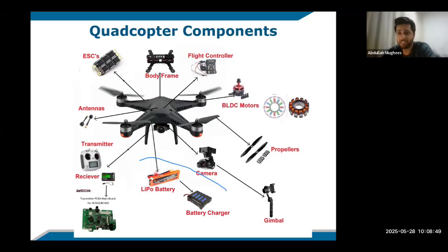The drones use specialized batteries. These are the LiPo batteries, lithium polymer batteries. And we do not use normal batteries for drones because they consume a lot of current. Like 40, 50, 60 amperes of current is just the normal case scenario for a little small drone as well. Well, not that small, but a laboratory sized drone easily consumes a lot of amps. So these LiPo batteries have the capability that they can provide you a certain high discharge of current.